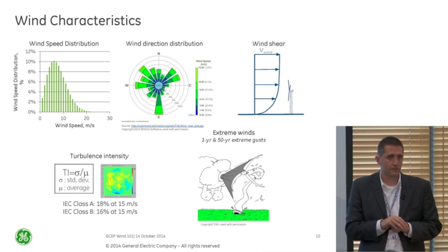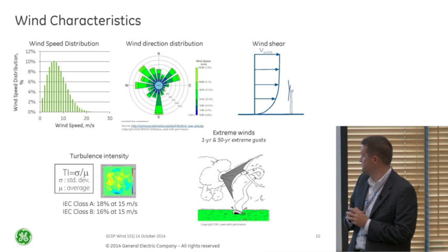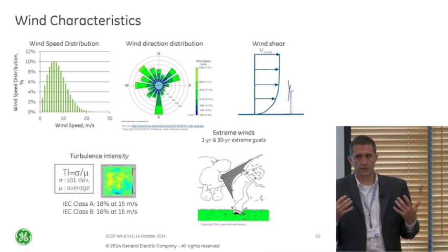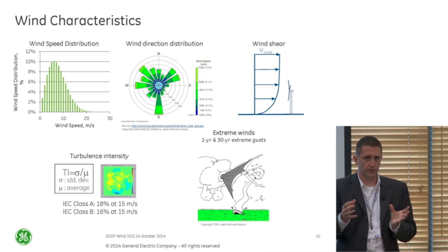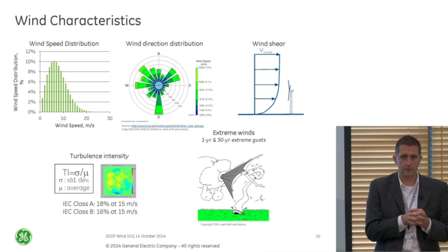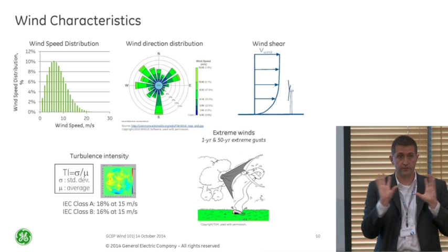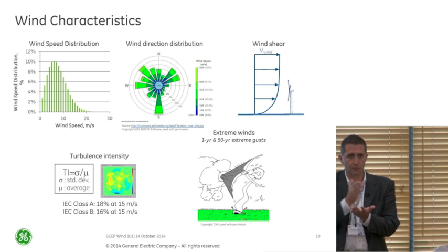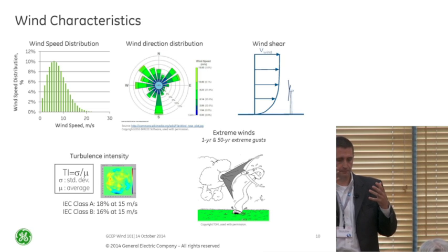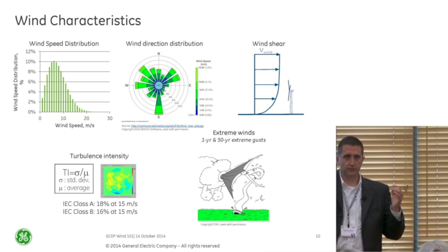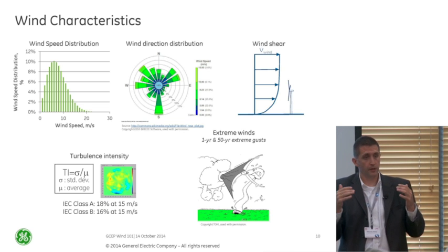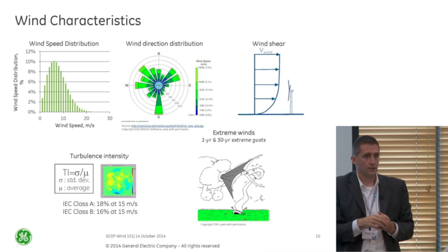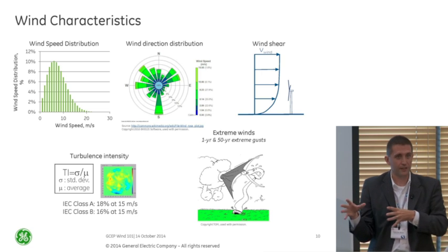But that's typically what's mostly seen in wind sites. Also, there's directional changes. So often you'll see it's mostly unidirectional, but there's different directional changes in terms of where the wind is coming from. This is important if you see huge amounts of differences in wind direction, specifically, not even on a map like this, but time-wise. Like if you're in some sort of weird mountain range where you have some valley and you might get wind shooting from different ways, that can become a big problem because now I don't have enough time to yaw back and forth to really capture that wind. So that can be a kind of a red flag in terms of the siting of that wind turbine.